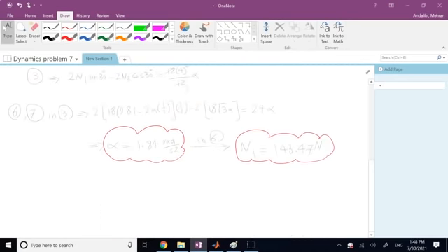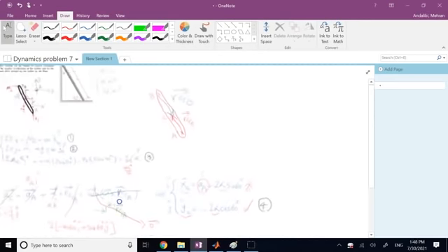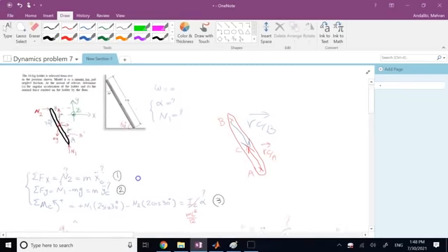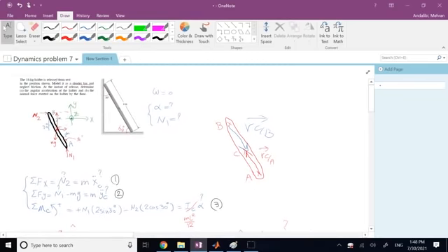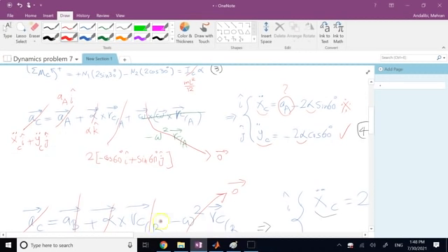Okay, so this is how you approach a 2D or planar kinetics problem of rigid bodies. You get all of the equations that you get from kinetics, and if you have more unknowns than these 3 equations, you need to get them from kinematics constraints, and you can get them through the acceleration motions, the relative accelerations, right?